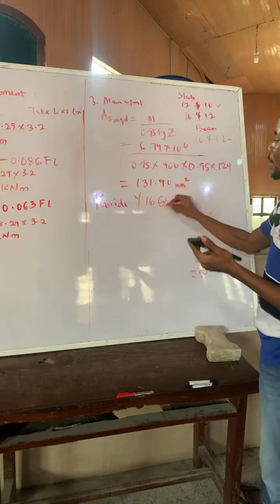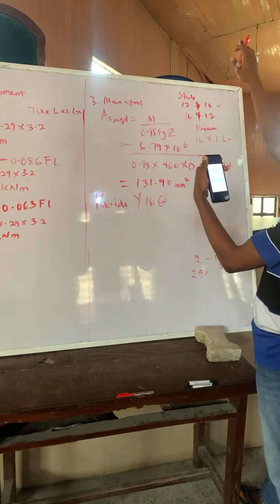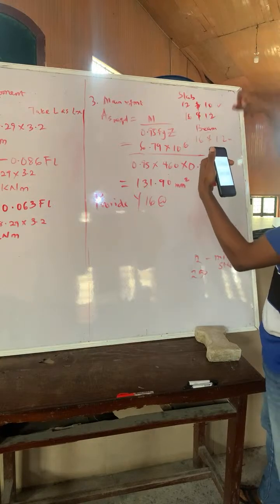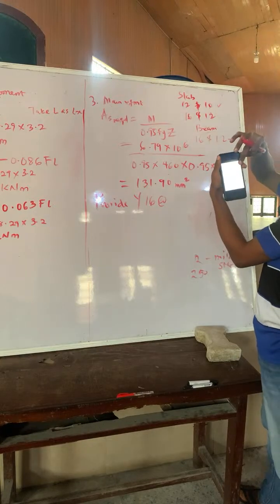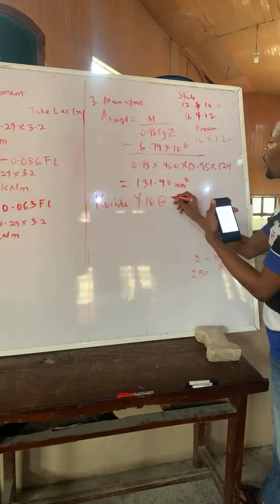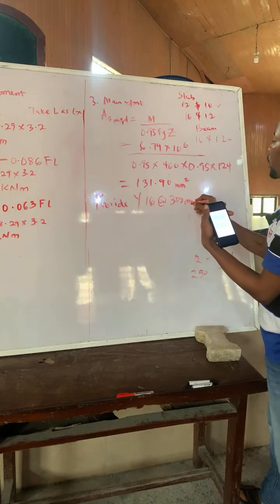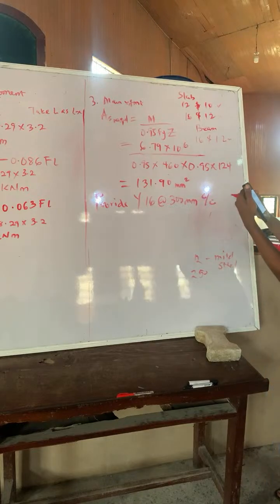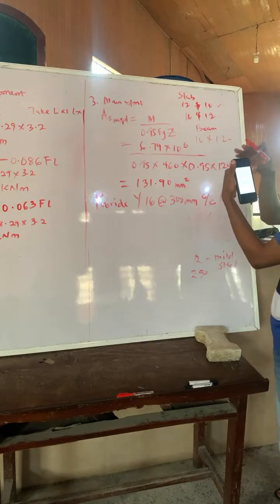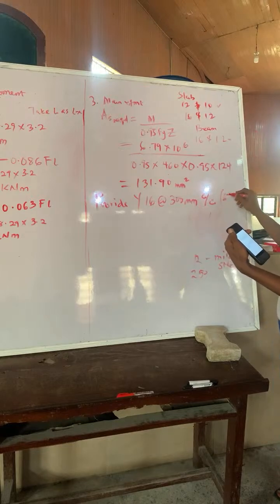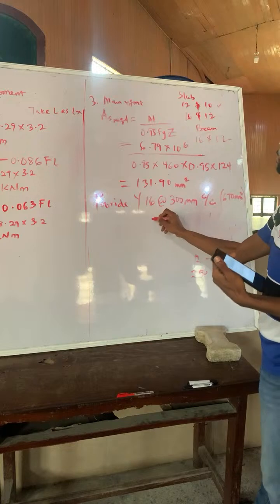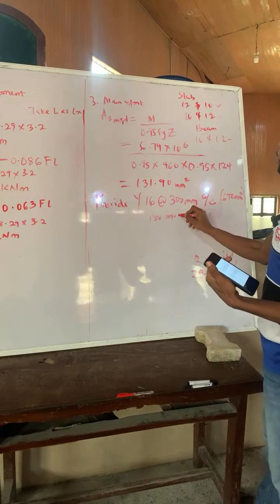Y16 at, we have 670, then you go up to your bar spacing in millimeters. It's under 300; the column is 300 up. So this is at 300 millimeter, center to center. Then you write your 670, 670 millimeter squared, then per meter run.